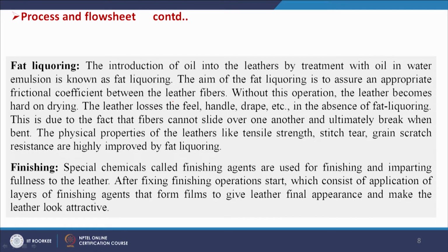Without this operation, the leather becomes hard on drying, and the leather loses the feel, handle, drape etc. in the absence of fat liquoring, and this is due to the fact that fibers cannot slide over one another and ultimately break when bent. The physical properties of the leathers like tensile strength, stitch tear, grain stretch, resistance are highly improved